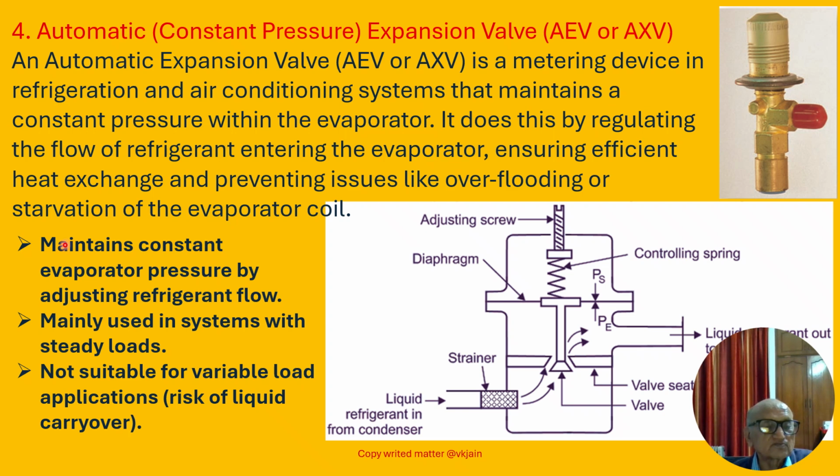The characteristic features are: first, it maintains constant evaporator pressure by adjusting refrigerant flow. Second, it is mainly used in systems with steady loads. Third, it is not suitable for variable load applications as there is a risk of liquid carryover.